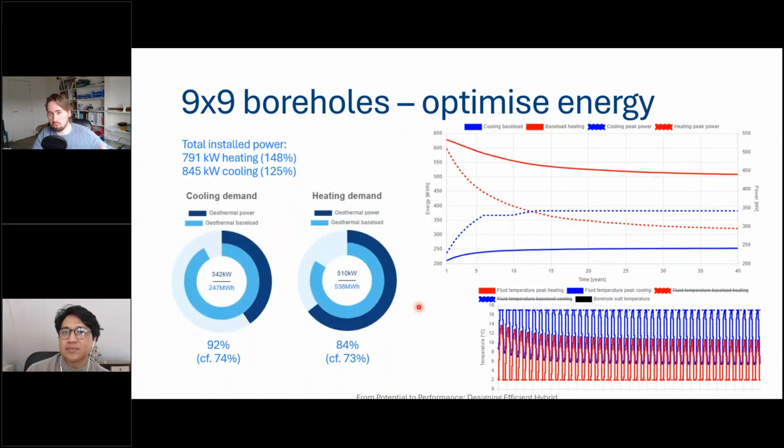So if the temperature of the ground goes below a certain value, we switch on the other technology. It's not so much about the design of hybrid systems, but the design of the hydraulic system: how you arrange all the technologies together, putting in the different valves and controls. It's independent from how you design the hybrid source. You can come up with 10 different hydraulic strategies for the same hybrid system. So your question is more related to good hydraulic design than good hybrid design, I think.